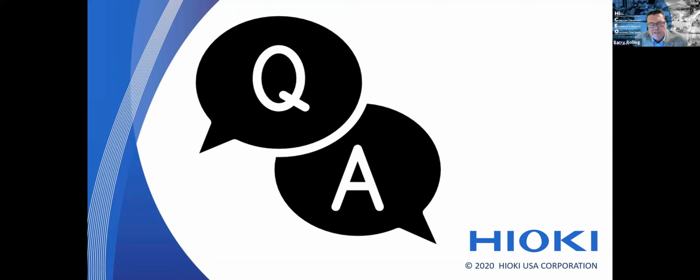Yeah, Chris, thanks. So in the past with the silicon devices, there are some lesser losses, but the two primary losses were turn-on transition and turn-off transition. That's that short period of time where your device, whether it's a MOSFET or a bipolar or IGBT, is transitioning from off to on and then from on to off.